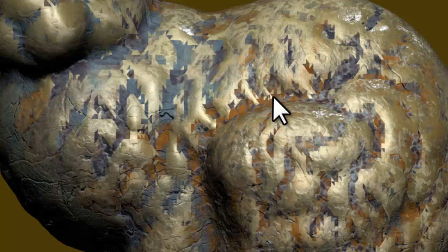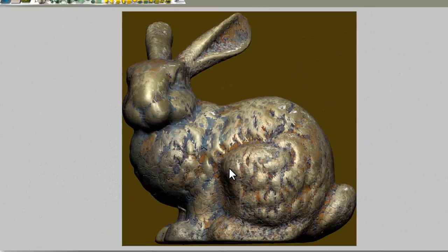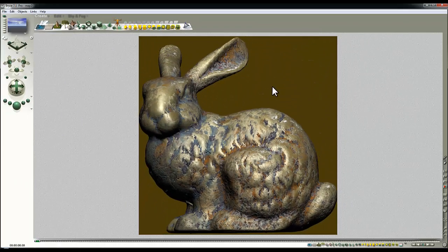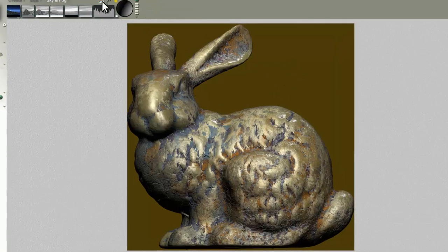Drawback is I can't get this out in 16-bit grayscale, and I need that to get the resolution for the height maps, which read in 16-bit grayscale, not 8-bit. So there's an additional problem to overcome there, but first let's get the height map. Now height maps are white where they're high and black where they're low, so I need this background to be fully black. That's easy to achieve.